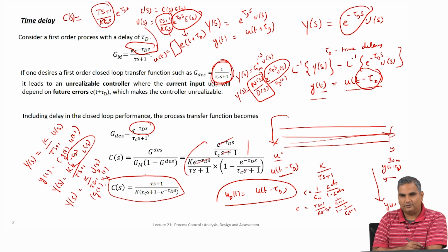You will notice that we have to bring in newer ideas to look at how to handle these types of transfer functions now, which are not your standard numerator over denominator transfer function form. So, what we will do is we will pick up from here in the next lecture and then talk about how you realize this controller and how do you think about looking at closed loop stability when you have time delay systems and so on.